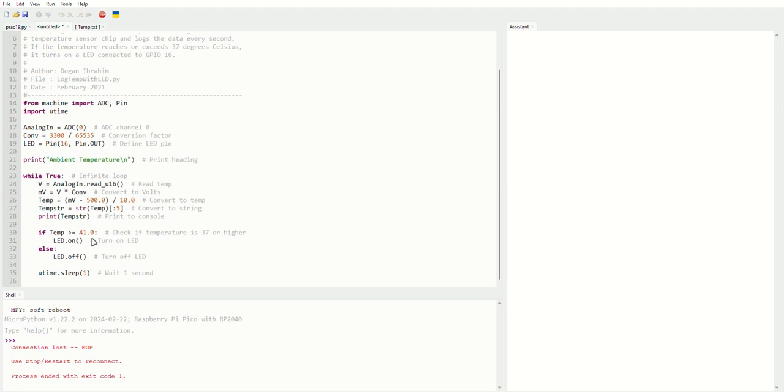it sends a 1 to the FPGA, and with that, the FPGA sends a 0 to the relay module, and the internal coil is going to receive a lot of electricity and is going to close the circuit. Once the circuit is closed, the electricity and the current is going to flow right into the fan and is going to start working.